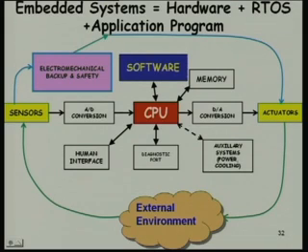but in a flash memory you write several kilobytes of data, read and written in one operation. So, these are more efficient and the writing occurs at 5 volts. Earlier in the EEPROM you needed a special EEPROM programmer which will generate, I think, 24 volts or something, right. Much higher voltage was necessary because tunneling of electrons is required, right. So, here the principle is similar, but much more improvised, and read and write occur in large chunks of data, several kilobytes in a flash.